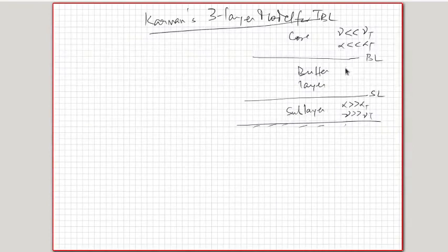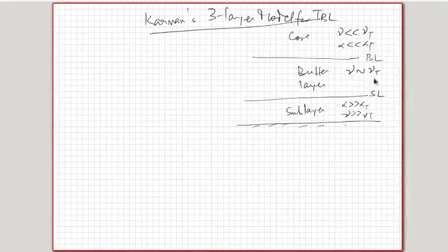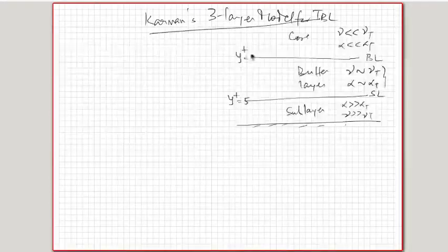And in the buffer layer, you say mu and mu t are of similar order, alpha and alpha t are of similar order, so they have to be kept and they cannot be neglected. And von Karman gave the limits of this as y plus equal to 5 and y plus equal to 30.